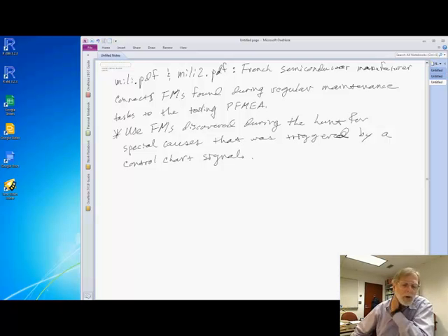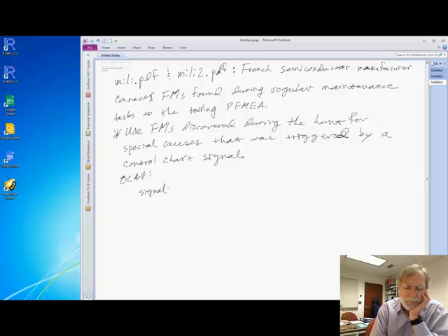So the control chart, either X bar or S or a range chart, gives you a signal, and your out of control action plan says drop the line. So here would be a classic out of control action plan. Signal. That's a start. Drop line.